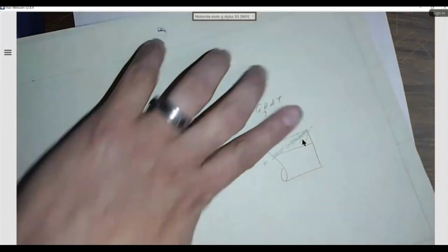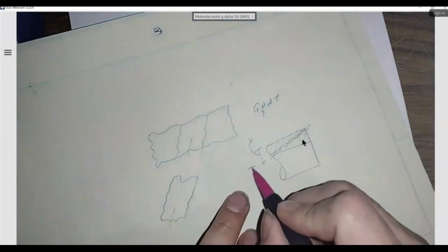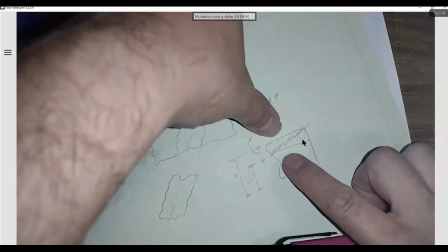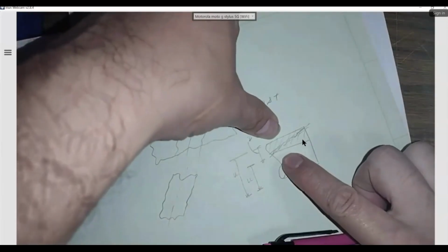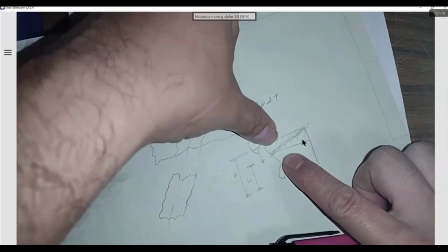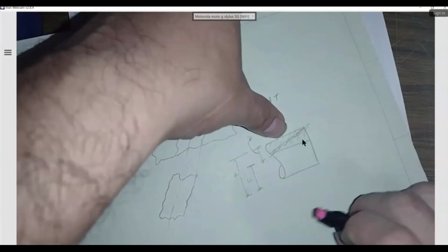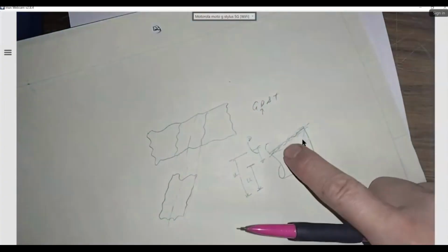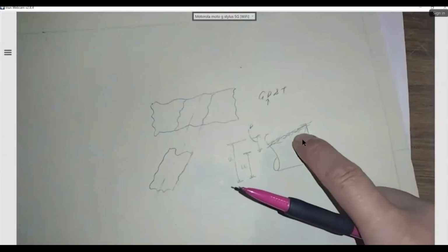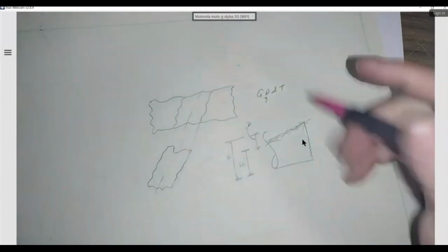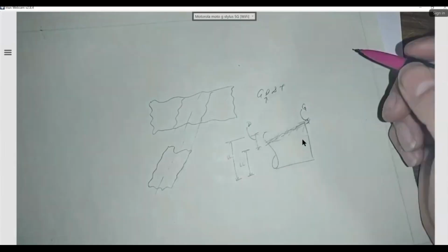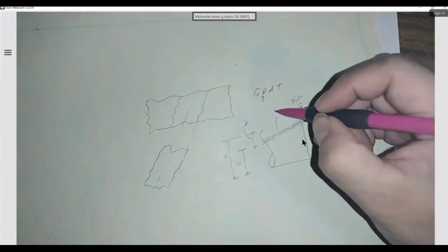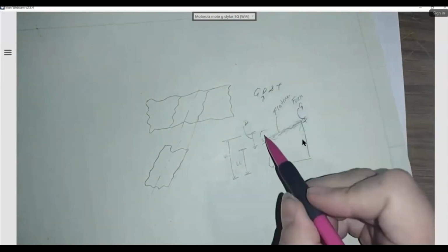I want to give you as much upper to lower limits. This is the lower limit, and this guy is my upper limit. I want my part to be within the upper and the lower limit, and if I want to refine the form, I get to do it within the tolerance that is within it. At this point, I have a tolerance zone that lives within the other tolerance, the dimensional tolerance. This one here is the G, geometric tolerance, but I'm only controlling the form. Let's call this guy flatness, and assume this guy is actually like a rectangle.